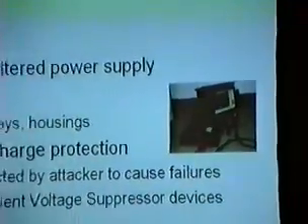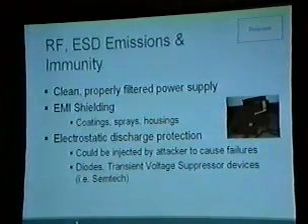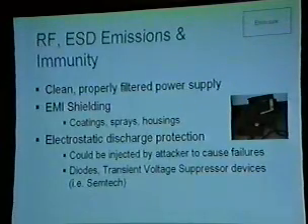But yeah, I do prefer sprays, and it's also because they can put them on at the manufacturing house of whoever's making the housing, so it's really easy. You don't really need to solder on any kind of RF shielding and stuff. So that's what I'd at least try at first.